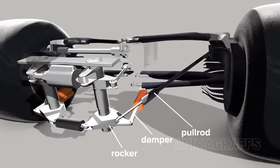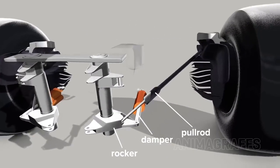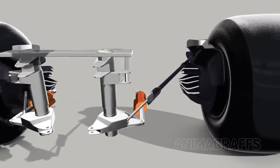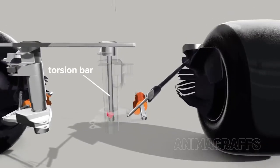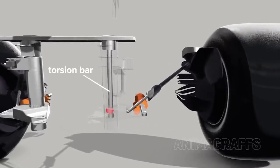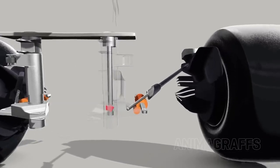The pull rod connects to a rocker and damper, which we call shock absorbers in normal cars. But instead of large coiled springs, F1 suspension uses a small metal rod called a torsion bar that twists under load. One side of the torsion bar moves with the outer cylindrical shaft, while the other side is stationary.